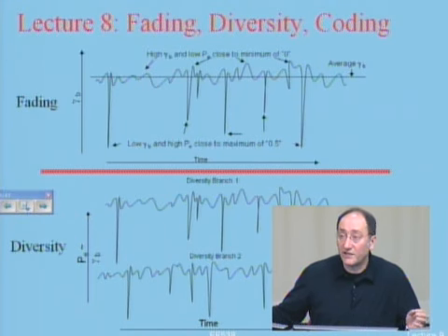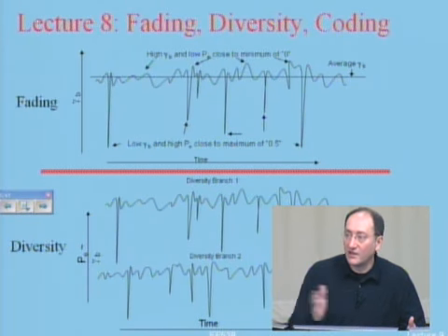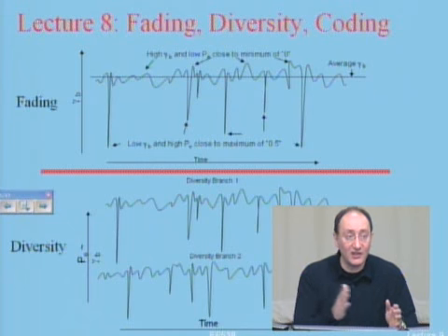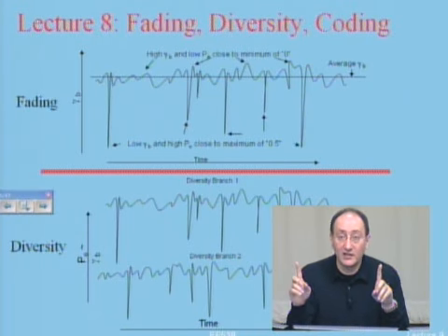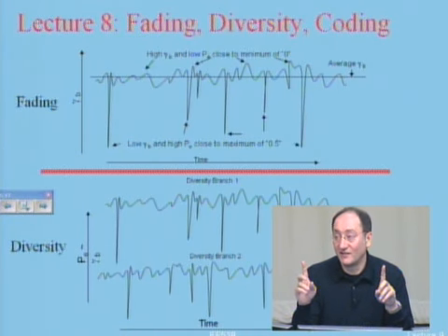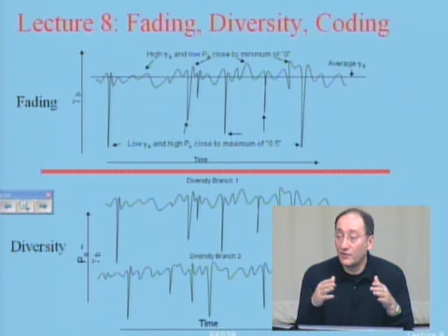How can I change the phase? How fast does phase change? You remember that phase changes as omega tau, and that tau is related to lambda. So if I go around lambda away and I put two antennas, they have like 2 pi difference in the phase. Okay, so I have plenty of room now for these paths to combine with.